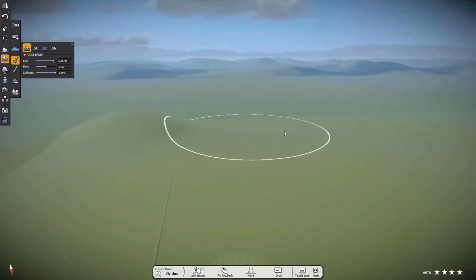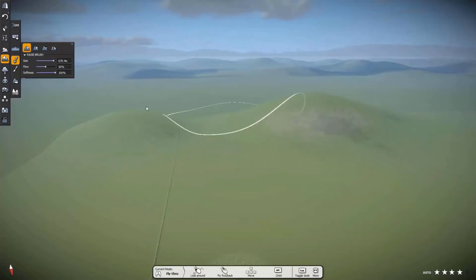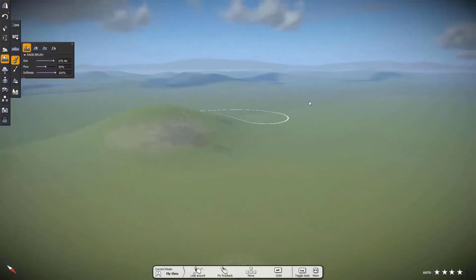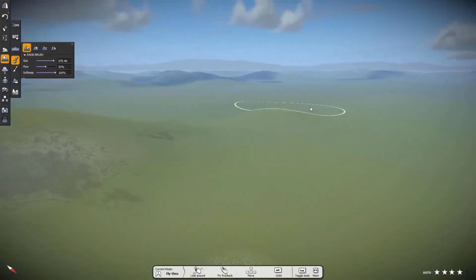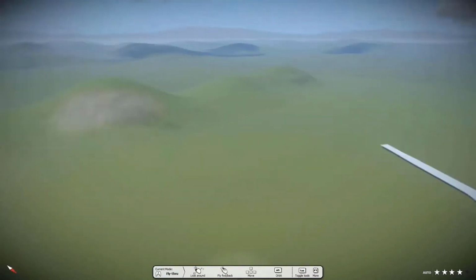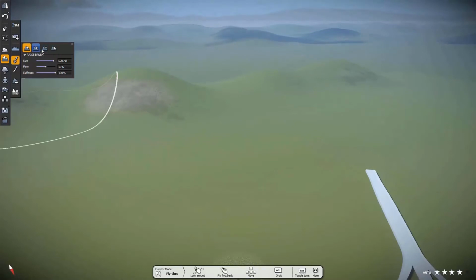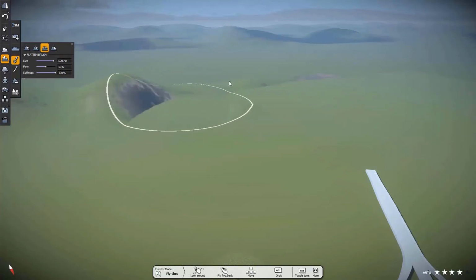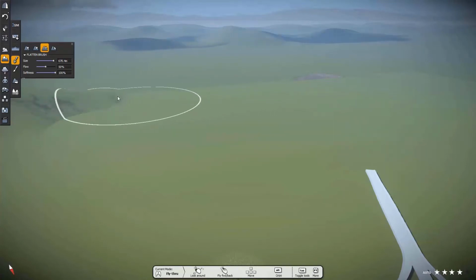So you just hold the left mouse button and you can raise the terrain. And once you go to the flatten, just take the reference and drag over the ground, and you can flatten the terrain very easily. So anytime you can manipulate your terrain according to the requirement.